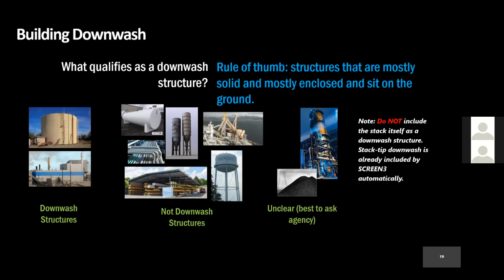But it's not always obvious if something is a downwash structure and if it isn't. And obviously the best way to get an answer for this is to ask your regulatory agency. Quick note, do not include the stack itself as a downwash structure. Now, stack tip downwash is an actual thing, and it's already included within SCREEN3. You don't need to add the stack itself as a downwash structure.